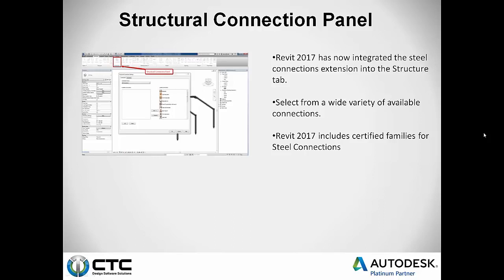So before, this used to be a Revit extension. You'd go to the Exchange App Store, download that, and they had steel connections, some other ones for rebar. But with this release of Revit now, as you could see from that image, the connection is now integrated into the ribbon there from the structural tab. So this is the new structural connection panel.